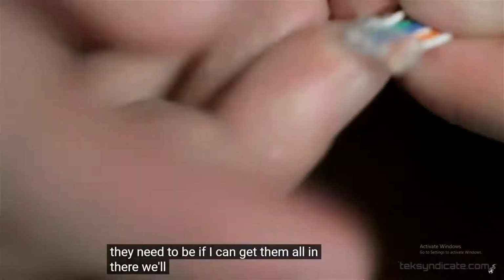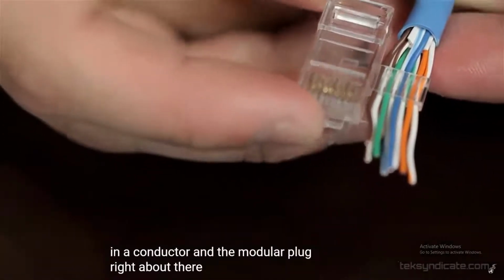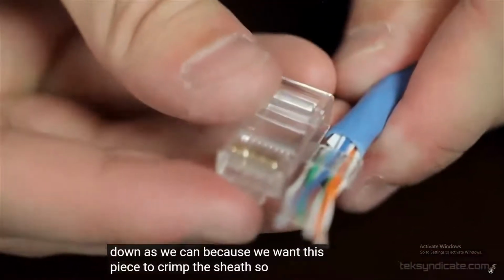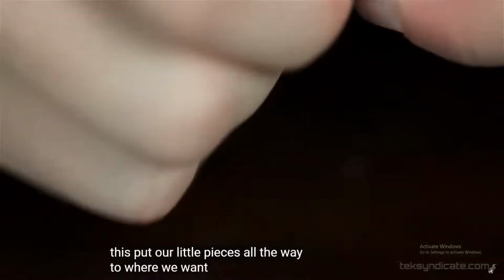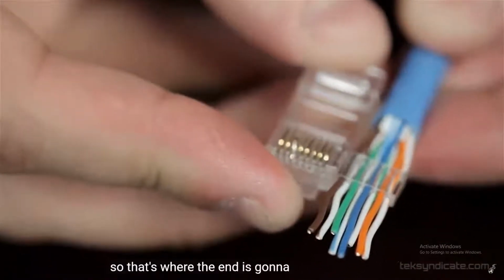Just wiggle it around a little bit. This piece and the finished product will end in the conductor or the modular plug right about there. So we want this as far down as we can because we want this piece to crimp the sheath. So what I usually do is I measure out where I want this. I put our little pieces all the way to where we want it to measure the length, because that's where the end is going to be.